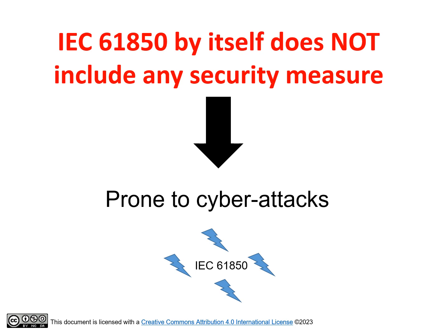The IEC 61850 itself does not specify security measures for communication protocols. Since it utilizes TCP/IP protocols, it brings all known vulnerabilities of TCP/IP protocols to the power system control and automation. The security of Ethernet-based communication protocols utilized in power systems is defined by another standard, the IEC 62351.